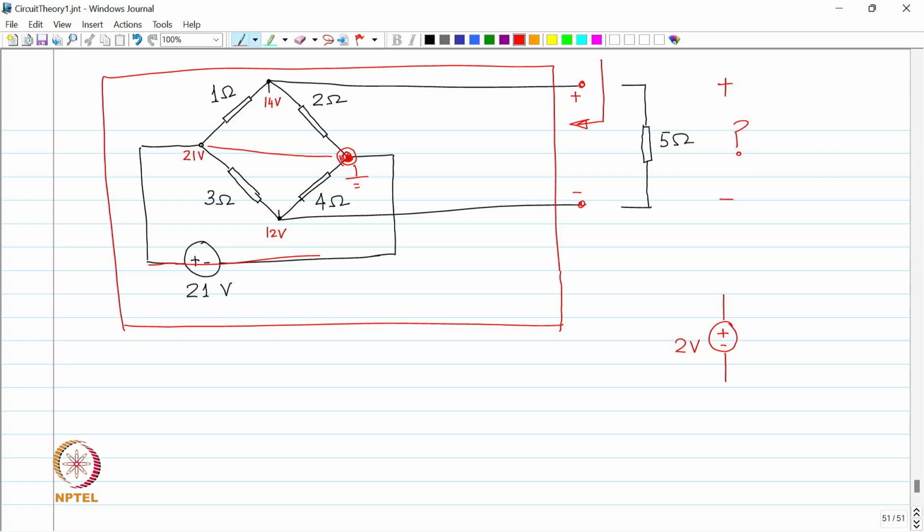You will find that measuring the resistance is just as easy in this case. What do you see? 1 and 2 are in parallel with each other, and 3 and 4 are also in parallel with each other, and these two combinations are in series with each other. So, your answer is 1 in parallel with 2 plus 3 in parallel with 4.